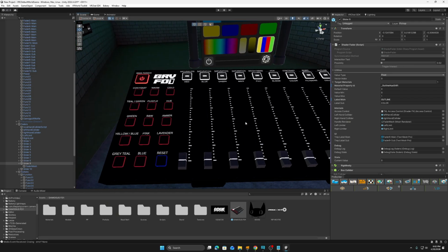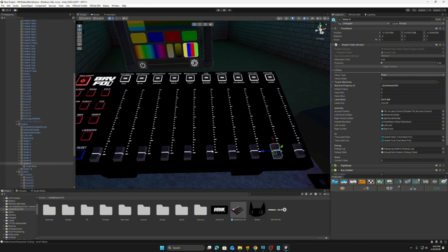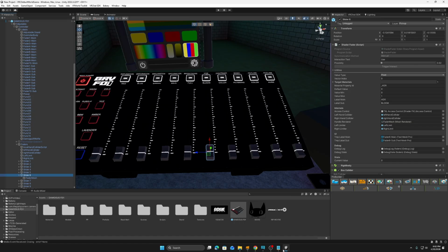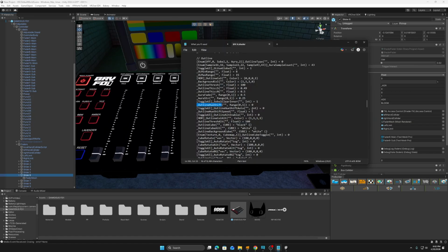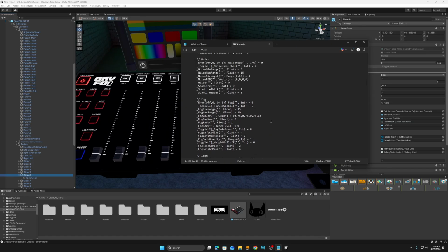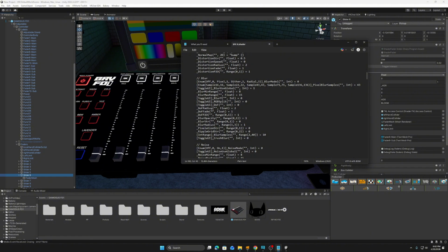And then, my personal preference, I'm not too much of a fan of the HDR bloom. So what I usually do is I go to the slider, bring up that shader code again, and I toggled on pixel blur, but I didn't add any effects to it. So that'll just do a basic blur. So we're going to do a blur strength float, range 0 to 1.